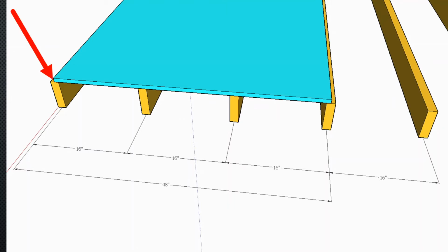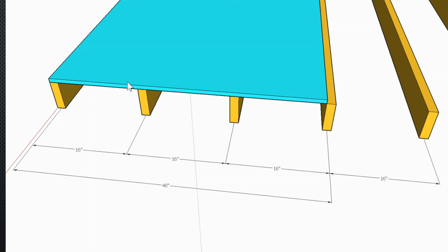And if you look over at this corner right here, this would be the outside edge of our shed, and we would have a little sort of a ledge there, a little gap on the outside of our shed. And that's not really good. You don't want this little gap here. You want it to be nice and flush so that this is a nice straight edge. So when we do shift that piece of plywood down, we're going to run into a little bit of a problem with this edge of it as we shift it.